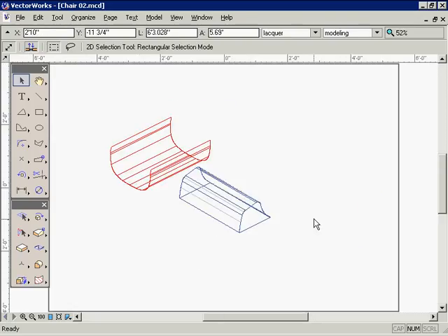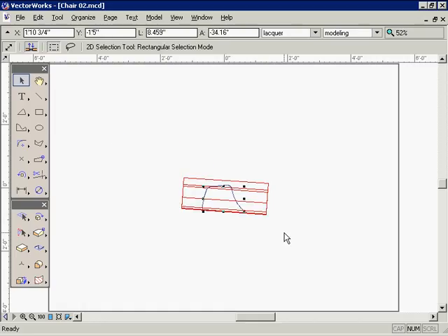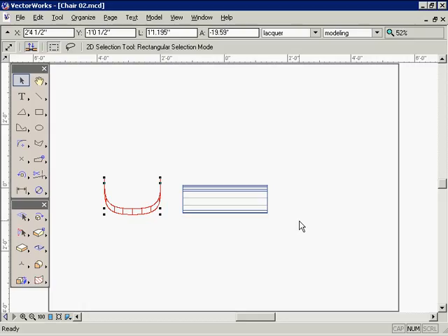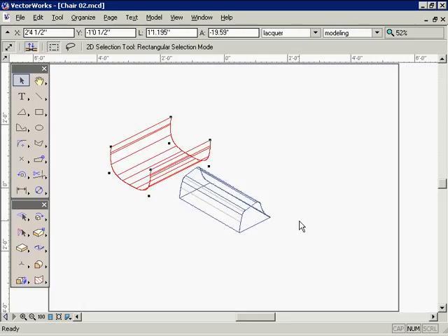I've already made two simple extrudes. This one has the profile of the seat when viewed from the side, and this one has the profile seen from the front. This second extrude is going to serve as a sectioning surface in the next step, so I've extended the shape up higher than necessary to make sure it cuts through the other one completely.